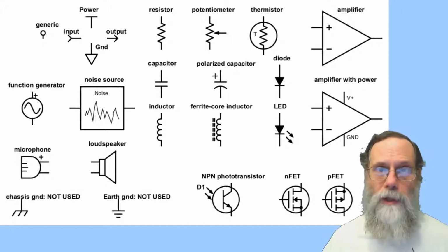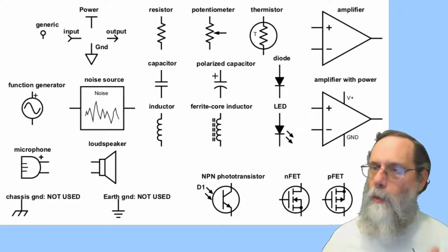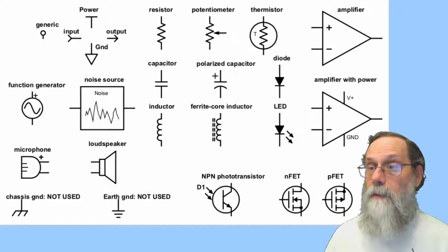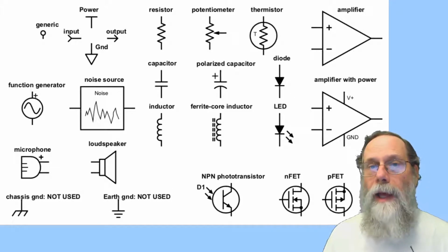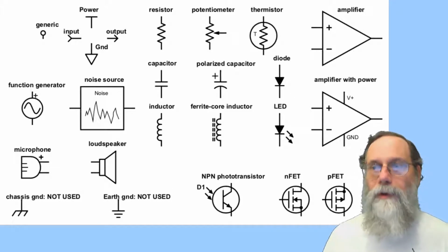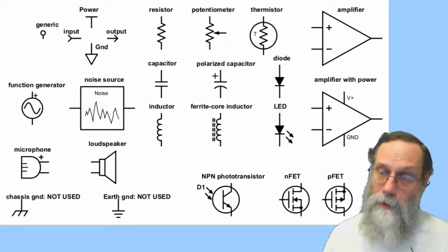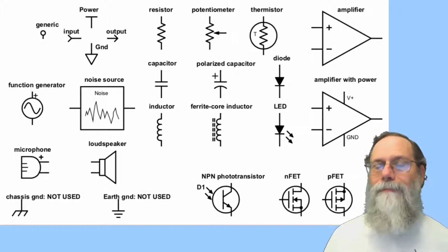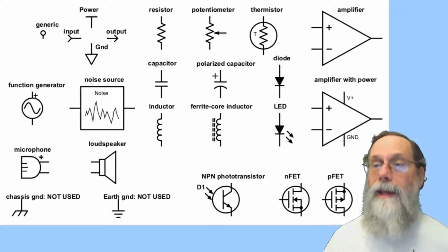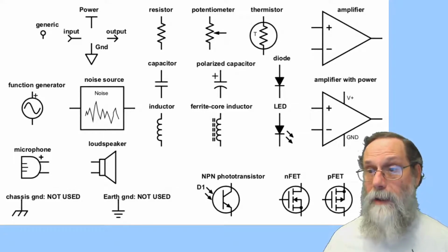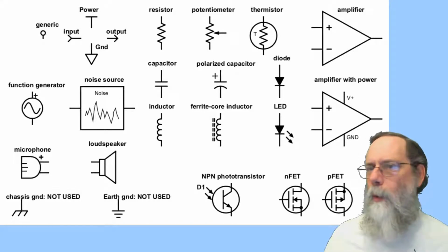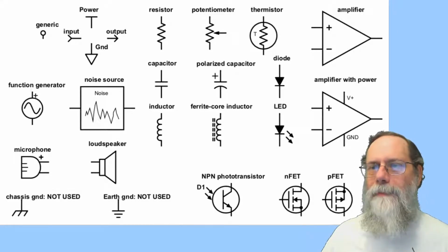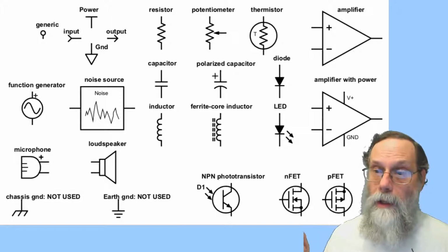The generic port, which is just a little circle on the line, you connect wires up to that line, that just gives a name to any symbol, any wire in your system. And you can use that for any sort of generic connection. It's this wire here. Anything else that has that name, if you've got another one of these generic symbols with that name on it, it's connected together. And sometimes it's done for connections on the same schematic because it's just too hard to draw a line that runs all the way across the page. Things get too cluttered, and so you just say, oh, this is this, and on the other side of the paper you put another one, and they're implicitly connected together.